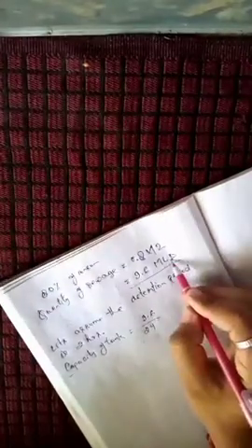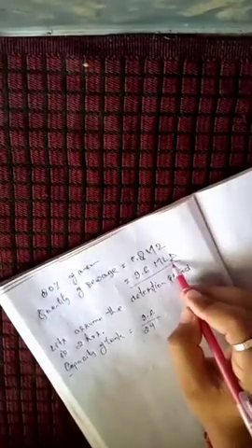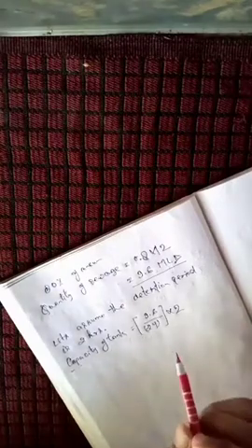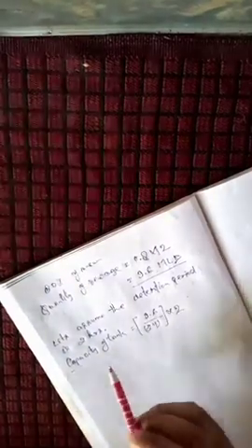This is given for the full day, which is 24 hours. That means this quantity will be produced per hour, and the detention period is 2 hours. That means the capacity of the tank must be the amount of sewage stored for the 2 hours.